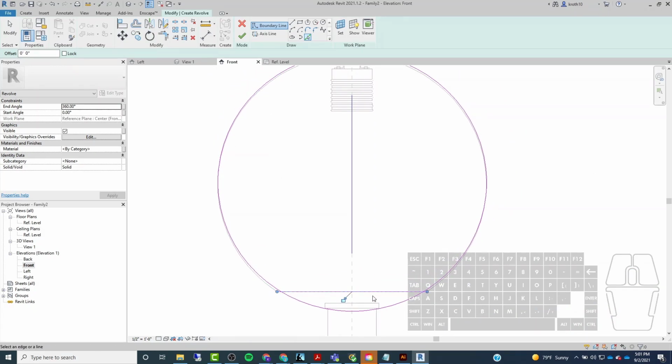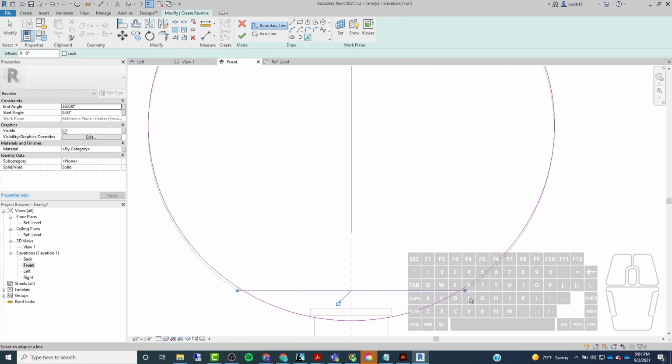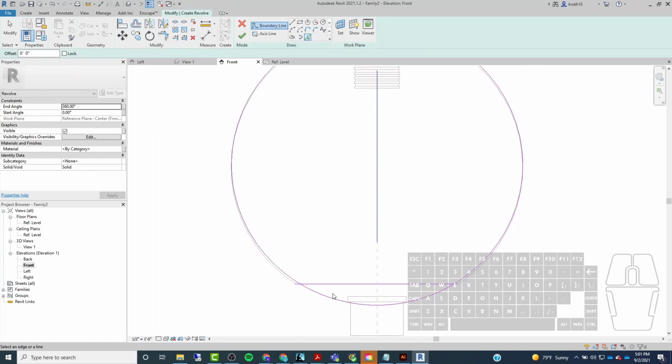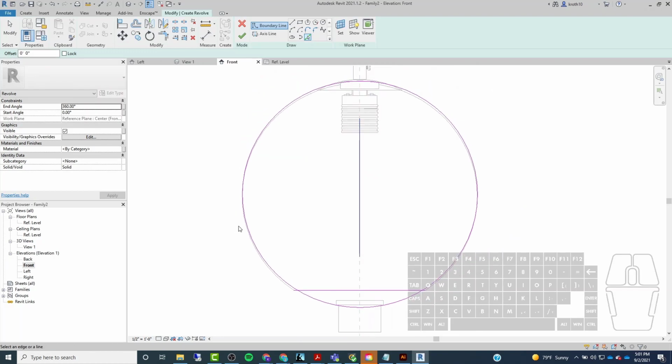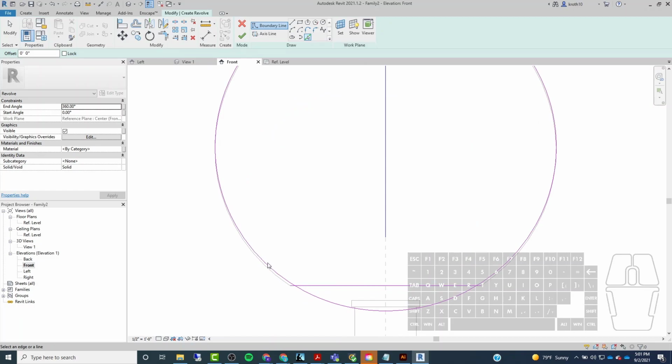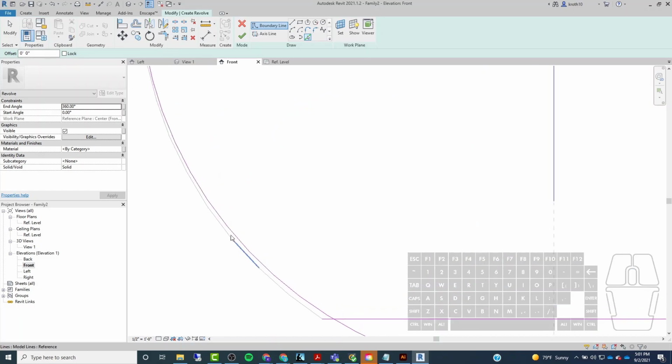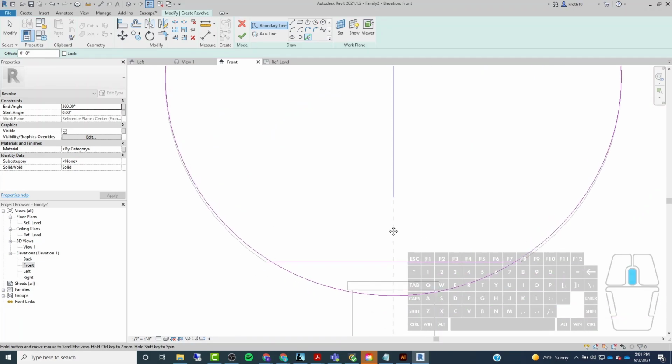But if you find line work that is just a straight long segment like this, you can totally just use the pick lines tool and just click on them and just use the original line work. That actually works really well if you're creating something with a lot of straight edges. So it's not as good for this where you have a bunch of curved segments, but things that aren't going to end up being subdivided with a bunch of segments are going to work really well.